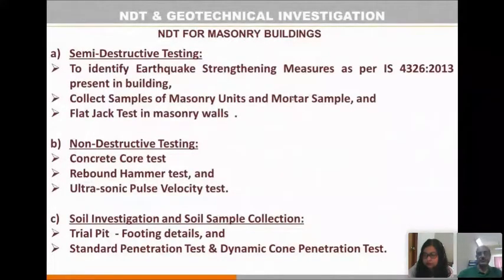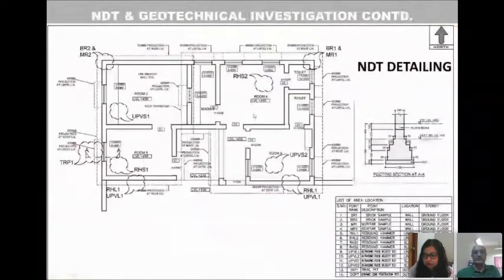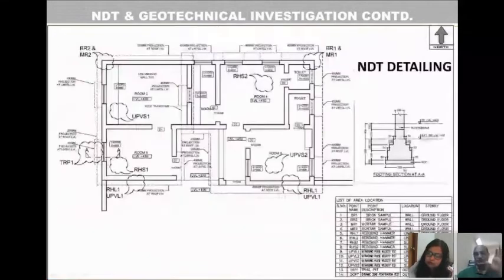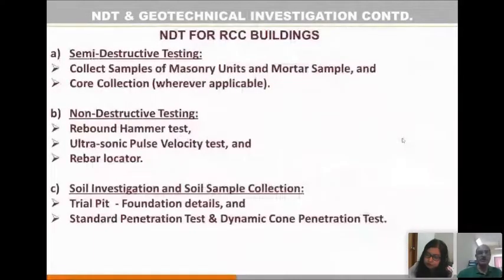checks. So usually the steps which are followed for the non-destructive test and detailing are represented in this particular drawing. Whatever entity you carry out should be marked properly on the drawings, as shown here, and along with that, you need to highlight those things in the scheduling as well. Most of the time foundations are ignored. You need to give proper attention to the foundation, carry out certain trial pits, and detail it properly on the drawings.